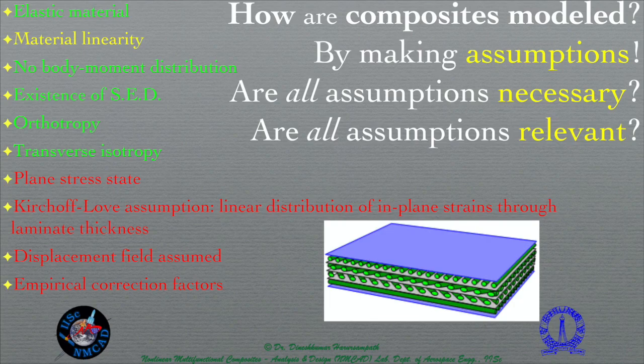In many situations, plane stress doesn't work, especially if you have thicker structures where transverse shear becomes very critical. In many situations, there are pressure loadings because of which there is transverse normal stress as well, which again is not accounted for in a plane stress. And in the simplest situation where you have, let us say, Poisson's effect, again you see plane stress situations might lead to erroneous results.